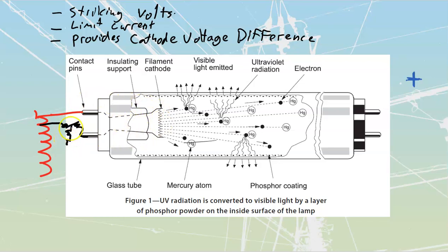It's not actually the thermostat that's sensing the tube, it's more that it's sensing the amount of current that's gone through this thing, and once this thing opens up, it no longer runs current through that cathode, because at that point, it's already warm, and so those electrons are easy for us to emit. So if you lose that, this thing opens up too soon, or maybe it failed to close, you will not get that preheat on your cathode.